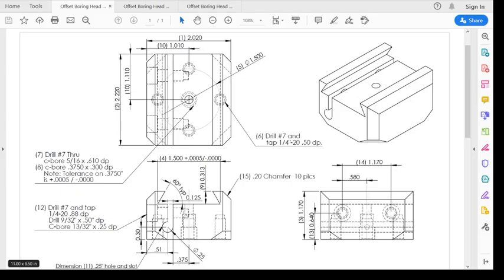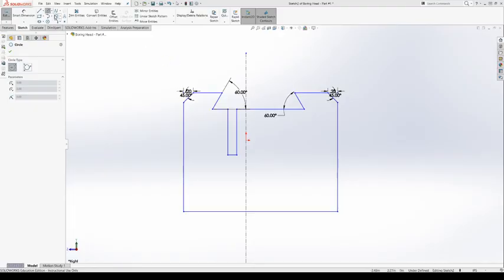So if you look at our print, we can see right here, the center of the circle looks like it is coincident with that, maybe, and tangent with this edge of our line, which works out. Yeah, we have a 1/4 inch circle with a 1/8 inch wide slot. So if I go back to SolidWorks here, I can go to my circle, and we basically have two different options to make a circle. I can make a center circle where I click first on the center point, and then my second click is going to be on the circumference of that circle, or I can do a perimeter circle where I just select 3 points that are on the perimeter of that circle.